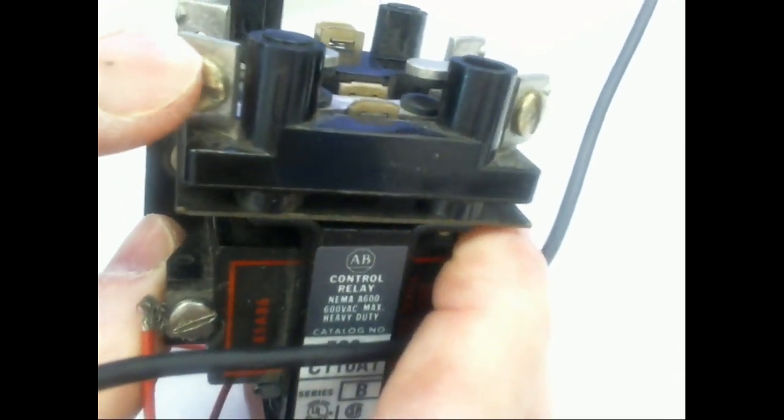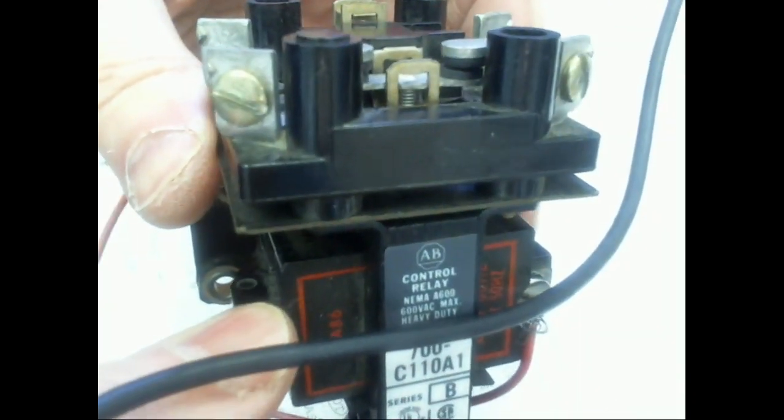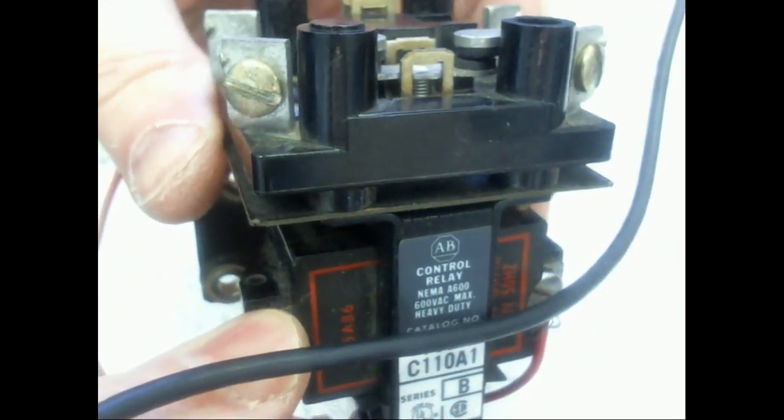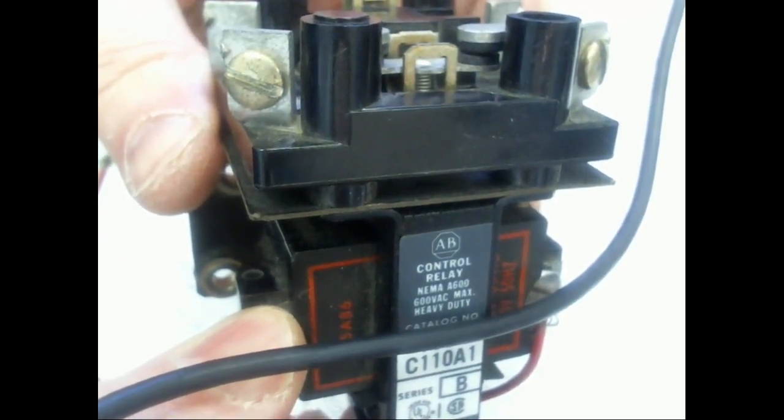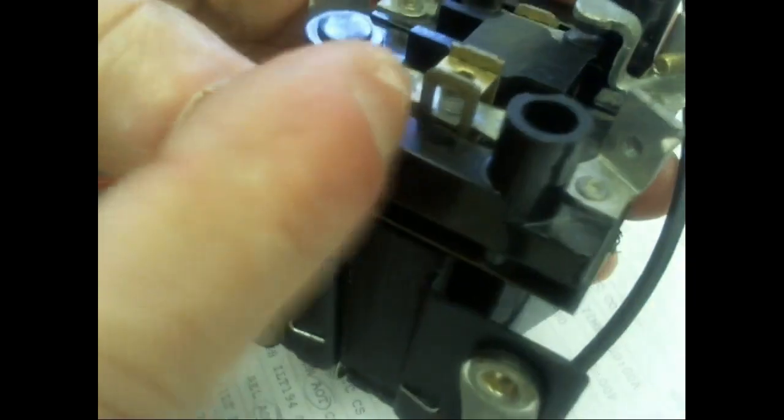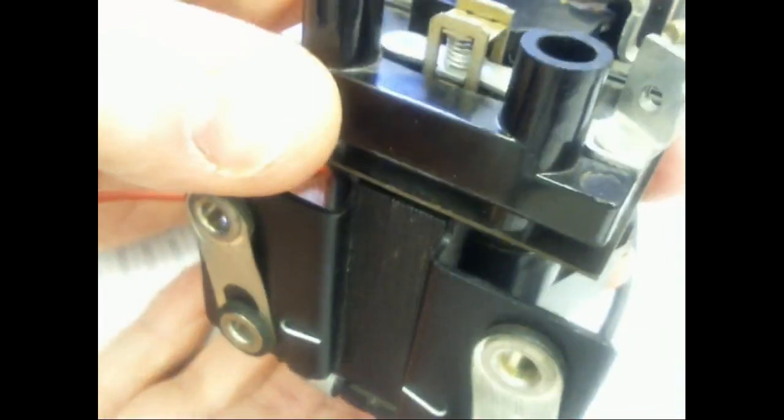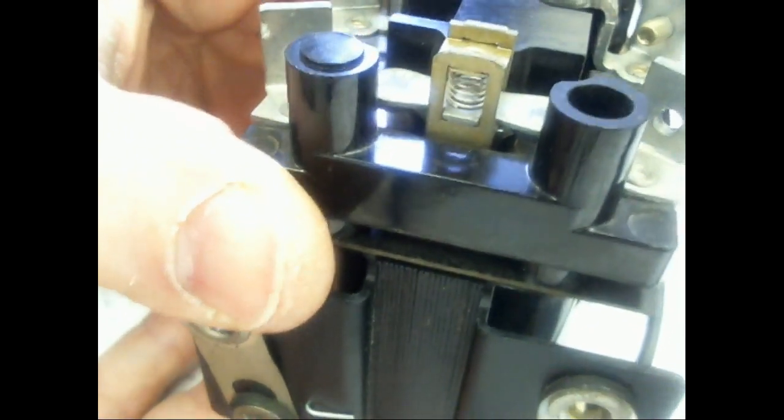Well, look what I have at the top of these things. I've got switches. Notice here's a switch right here. Can y'all see it? I'd hook one wire right there and another wire right there. When I put energy on, these switches come up and they close against each other. And when I take the power away, what would they do? They would open. Now, if we look at this set of contacts over here, these are already closed. So right now, with no power on the solenoid, this switch would be closed. And when I energize it, this switch right here opens.